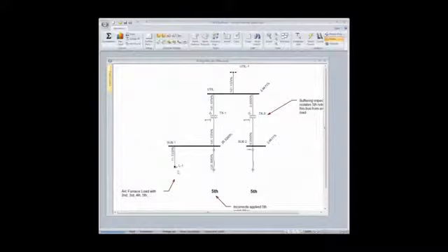In this case, for this type of load, you're going to find yourself having to filter very low, and start very low to make sure you accommodate all of the harmonic characteristics here. Again, we probably start filtering at the lowest one, at the second, believe it or not. These arc furnaces are very interesting. The second, third, and fourth, they're all positive and negative sequence. The transformers feeding these are typically delta connected, and these harmonics just come manifesting right out of it.